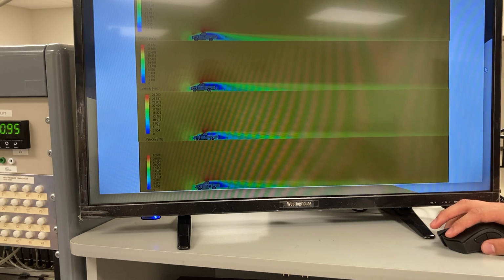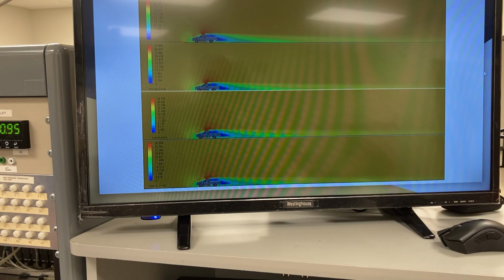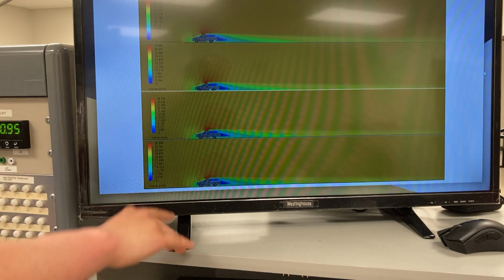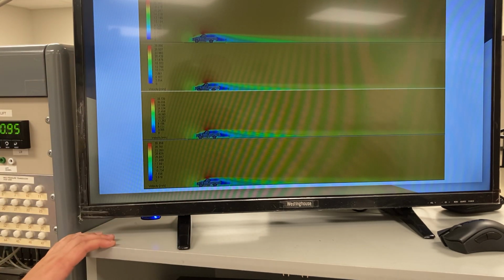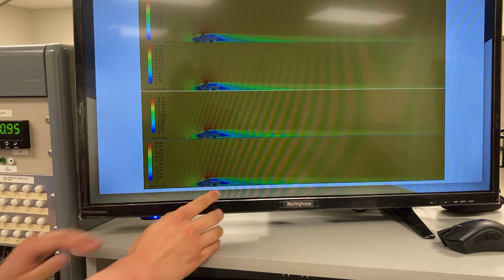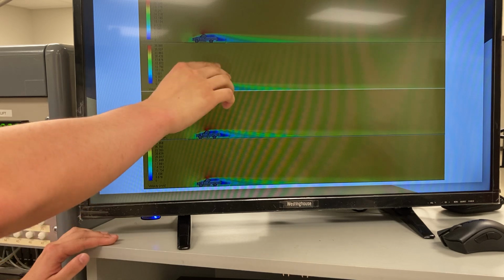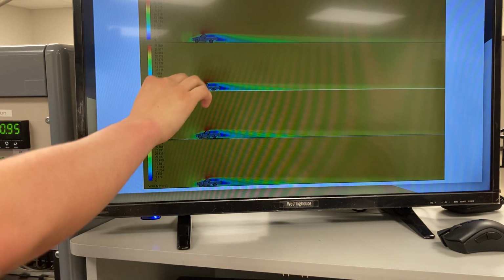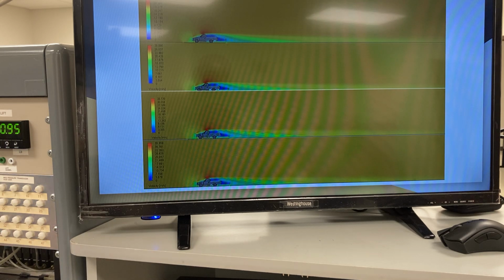The same contours at different speeds. And a comparison. Here we're comparing the tonneau cover from 40, 50, 60, and 70 miles per hour. So we can see the general velocity profile of the bed remains the same, but of course at the top here, where the velocity is at its highest point, the area will increase with speed.